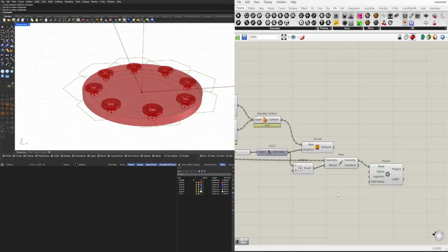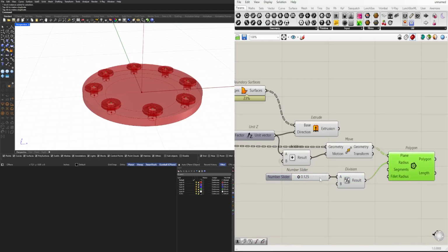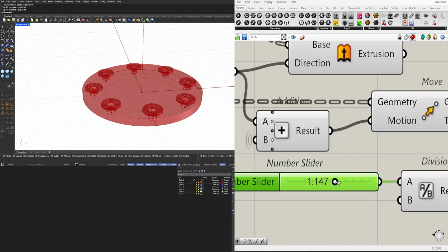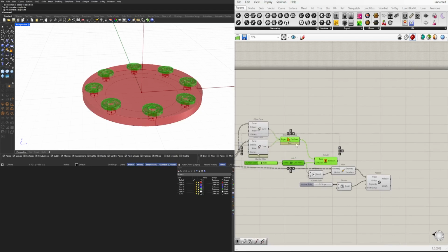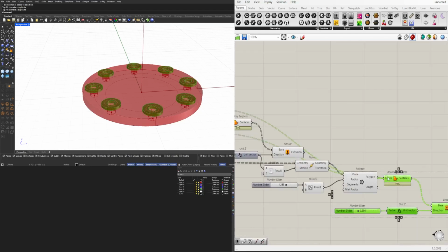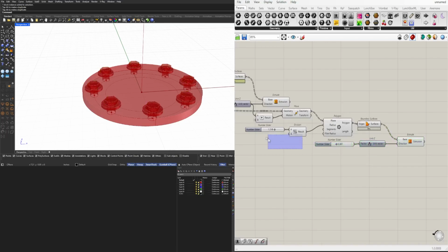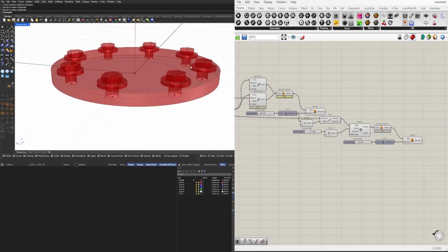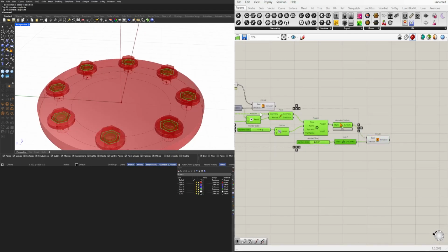Now let's change the size. And then if you divide it by 2, we'll get the diameter. We'll do a max of 2 here. And then create a boundary surface and extrude it again. So using these 3, I'll copy it over. And now we've kind of set the stage for what we want to do up here, but also to know how much we need to offset to make sure that it doesn't intersect with at least the bolts here. So this will be hidden.